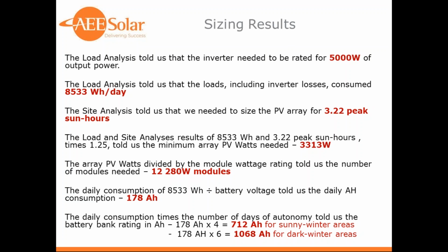And so it's really important to do that kind of assessment so you know what your total energy production is. Batteries are pretty expensive, so if we can produce more energy more of the time and reduce our storage requirements, that's always going to be an economical thing to do.